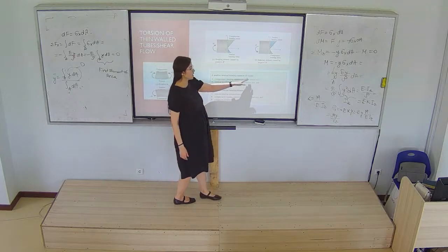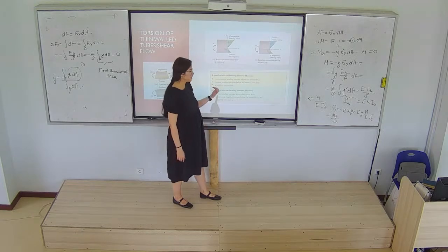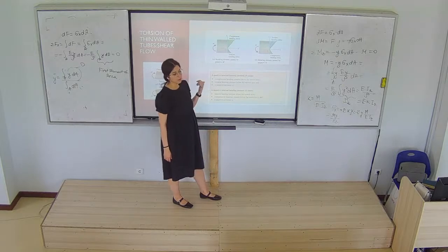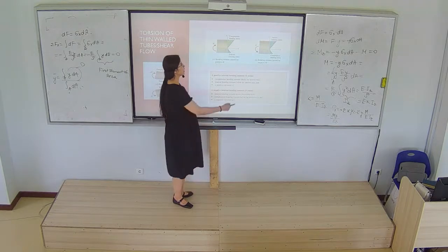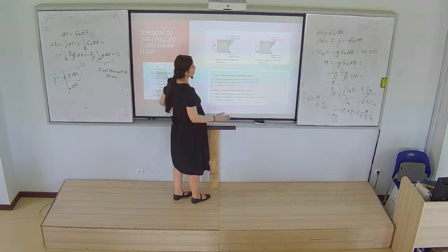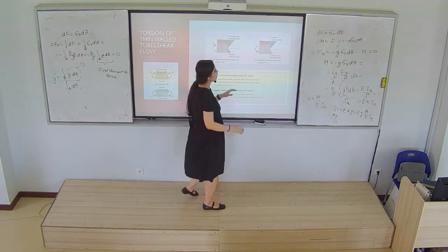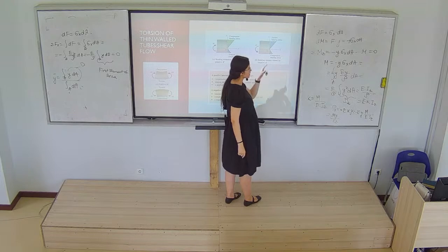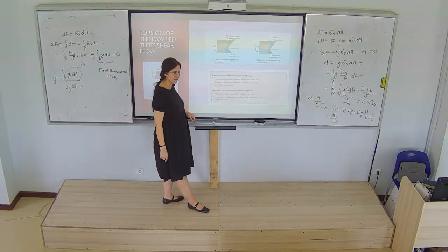Positive internal bending moment causes compression bending stress above the neutral axis and tension bending stress below the neutral axis, and positive curvature. It means that if the moment is positive, our curvature will be positive. If the moment is negative, our curvature will be negative. Here there are bending stress conventions. If the moment is affecting this side, our stress is minus. If the moment is affecting this side, our stress is plus here, minus here. That's it. Did you understand?